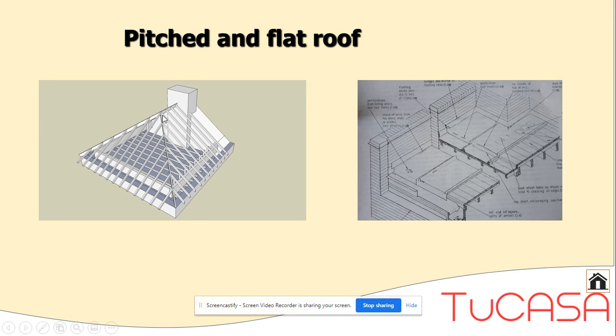This is what's called a hip roof, and this is a hip timber here and a ridge timber. All these components are built on site, relying on the concept of triangulation to stiffen the roof structure. You'll find various diagonal braces as well, hopefully, underneath, and also in modern truss roof constructions.